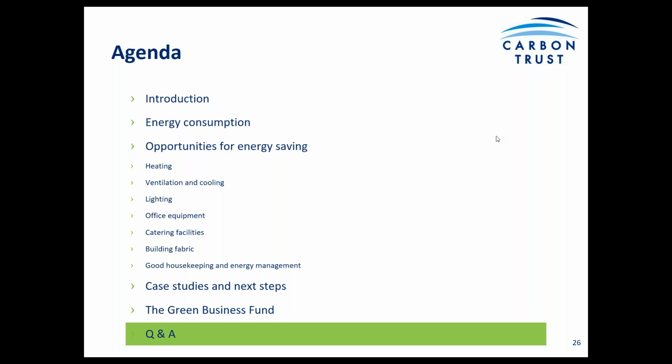Depending again on the type of site, it may be that you would take the view that that's not actually the most appropriate solution for that site. So, for example, if you're trying to use a gas central heating system to heat a large warehouse site, that's usually not optimal. Usually there we look at something like gas-fired warm air heaters. So with any technology solution, it's important just to make sure that what's being specified is actually appropriate for the site.